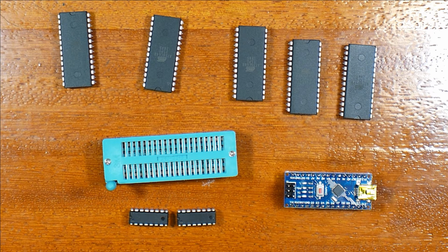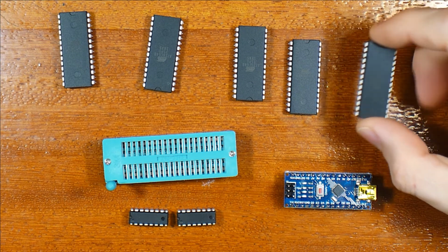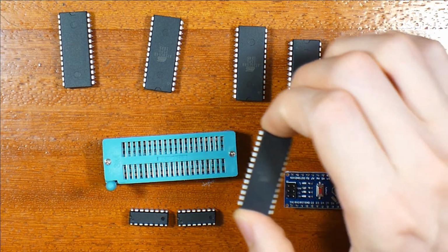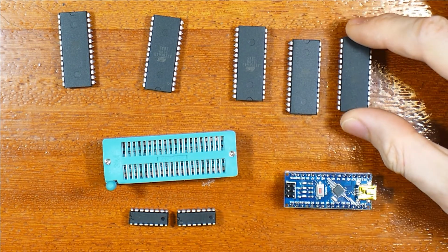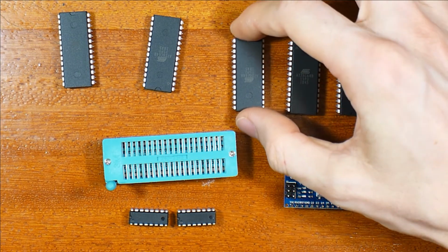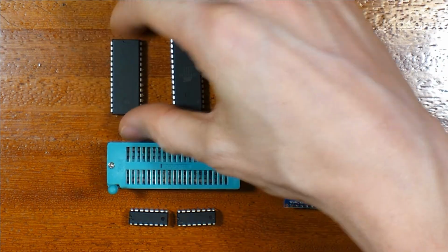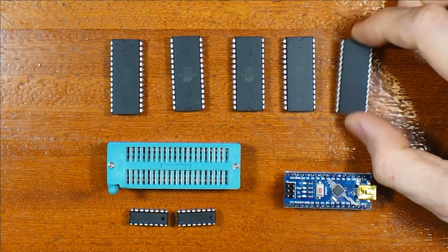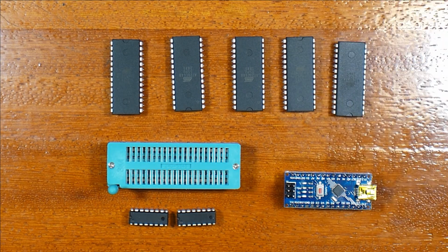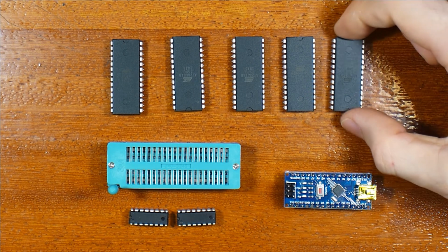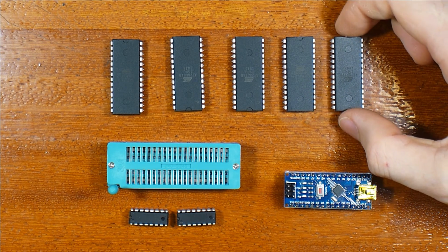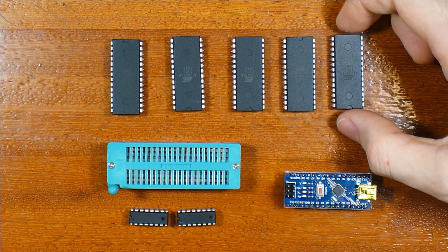And why would we use a parallel EEPROM nowadays, since they're almost obsolete and have been substituted by serial EEPROMs? The reason is they are very good to replace combinational logic, in the way that they have some inputs, that is the address, and the output that is generally 8-bit for an 8-bit bus.